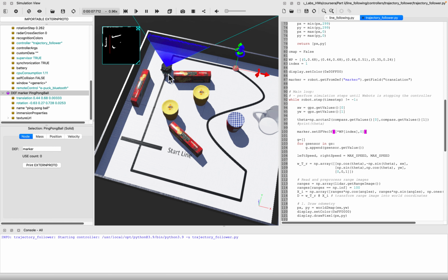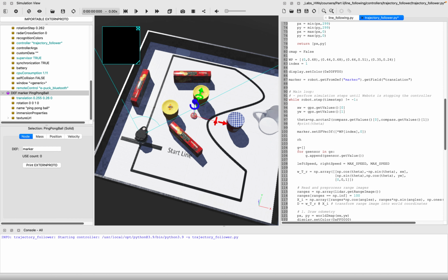Now what we can do is compute the arrow. The arrow is both distance and angle, and we can start with the distance. For this we will choose the Euclidean distance and call this rho. The Euclidean distance is the square root of the squared differences between the x and y position. So we have the x position of the robot, and the y position of the robot, and I square both of these.